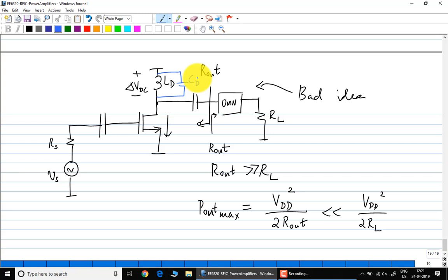Any other questions? Okay, so now I think you know how to design a linear CMOS PA, right? If you need to do input matching and output matching, do you know how to do it now? It's very straightforward, right? Can you calculate the gain? Of course, you have a gain of half at both input and output because of matching. Then what you will get is actually gm Rout, or gm R. Well, if you don't have a matching network, gm RL by 4 is what you will get. That's the overall voltage gain.